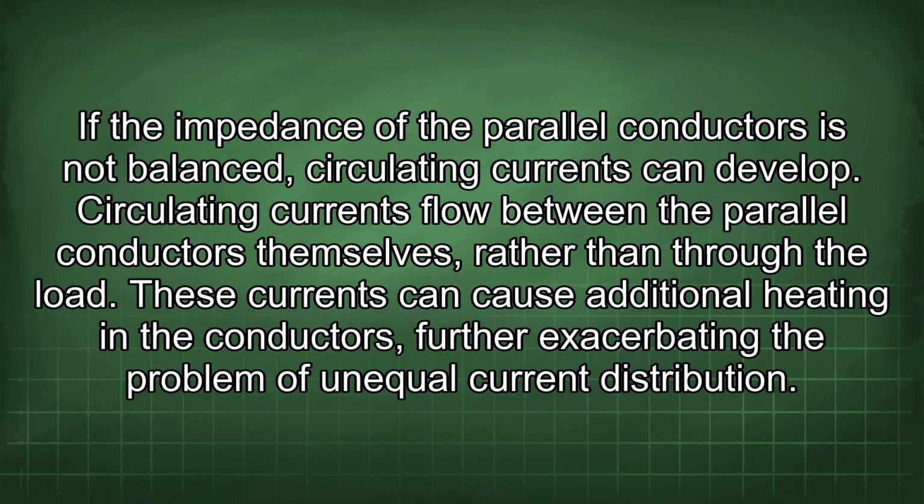If the impedance of the parallel conductors is not balanced, circulating currents can develop. Circulating currents flow between the parallel conductors themselves, rather than through the load. These currents can cause additional heating in the conductors, further exacerbating the problem of unequal current distribution.